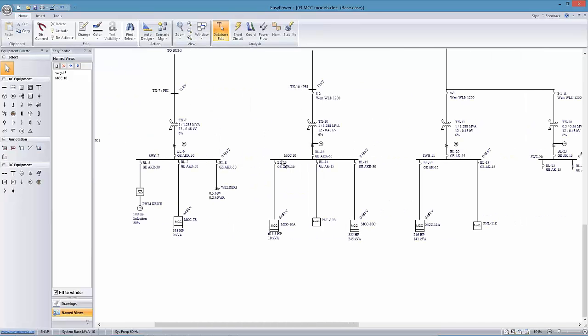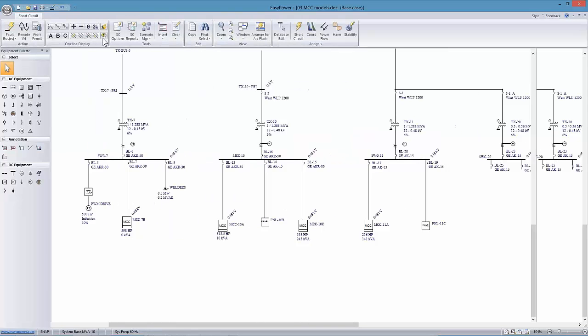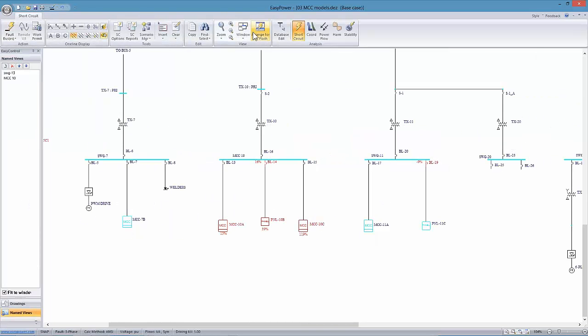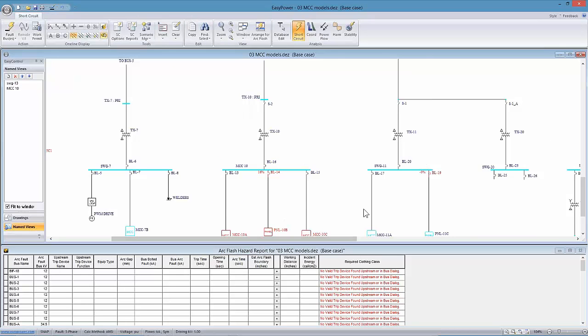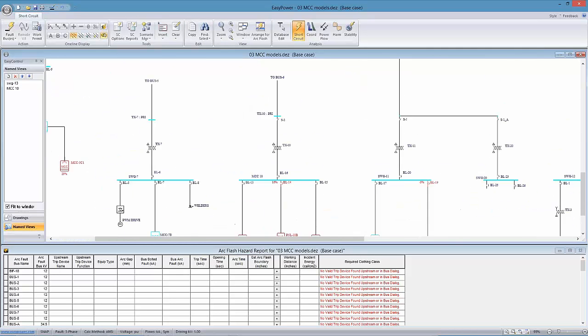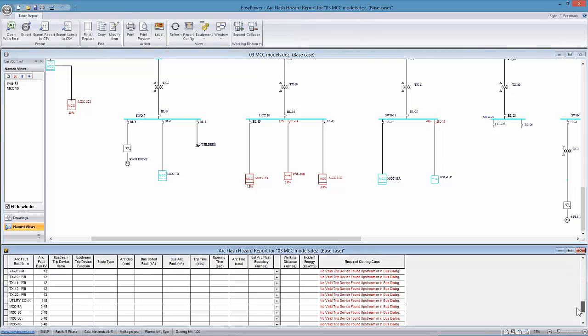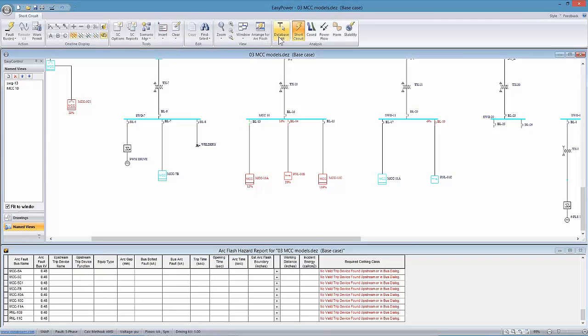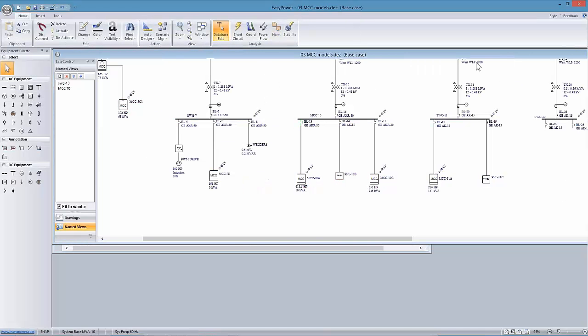Still, when I go to calculate the breakers, so let's go ahead and do my short circuit, fault the buses, arrange for arc flash. Okay, so what I'm trying to do here is point out that I will still get individual labels. If I had my breakers set up, I will produce individual labels for each of the downstream loads, which is the drawback in going to the icon methodology. All right, let me jump into the icon methodology.